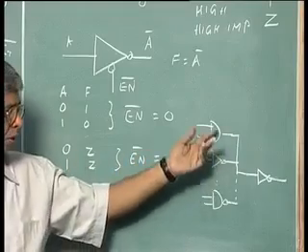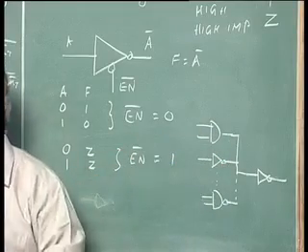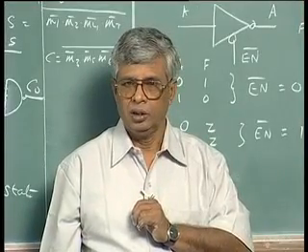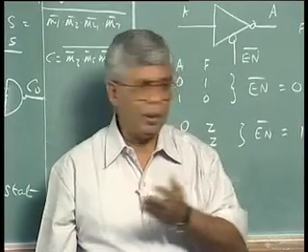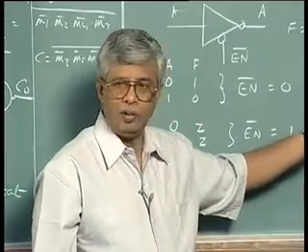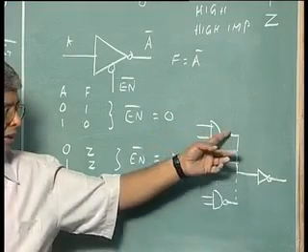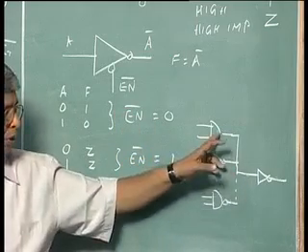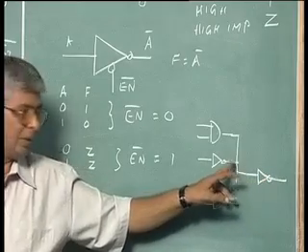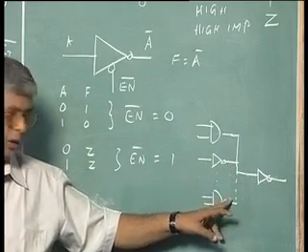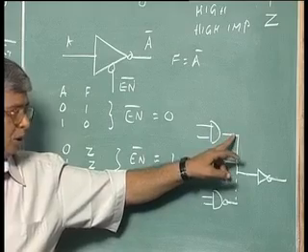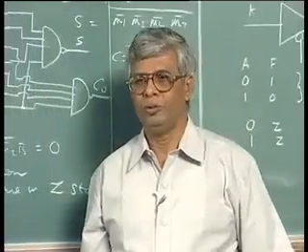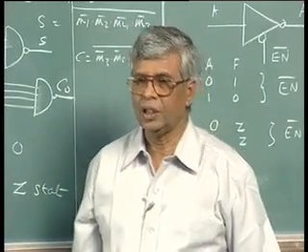I can do it, and when I don't want it I can remove these ICs. As I said, that is not a good solution, not a practical solution. If I don't do that, what will happen is, whether this is high or low, all of them have to be high or low. If this is high and all of them are low, low is 0 volts, that means practically ground. So I am trying to push this high voltage into this, and that time this is low and this gets grounded, this also gets grounded. So whenever I am trying to pull this up using the output of this, because it is high, these two gates will pull it down to 0, right? These are the problems.